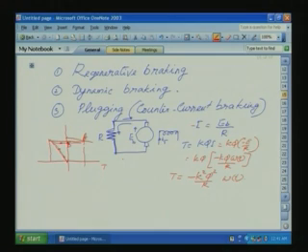That is called plugging. So in high dynamic performance applications, regeneration is the best way, where some of the power is taken back, but the cost of the system can increase. Or quick braking by dynamic braking, where it is dissipated. This can be used for speed control also, not only changing the speed up to 0, lowering the speed also can be done. So with voltage control, how effectively, with good dynamics, we can control the speed, that we will study now.